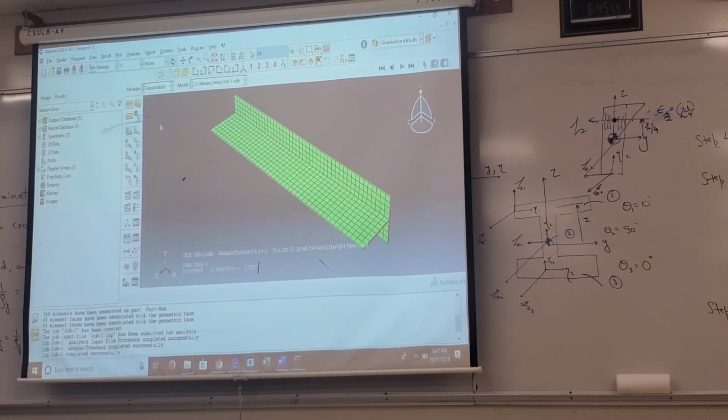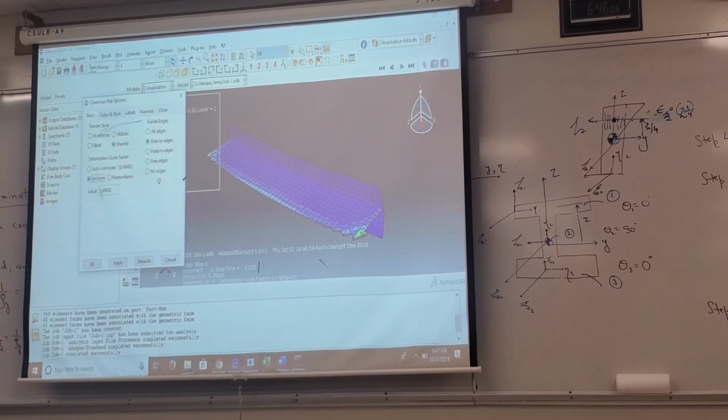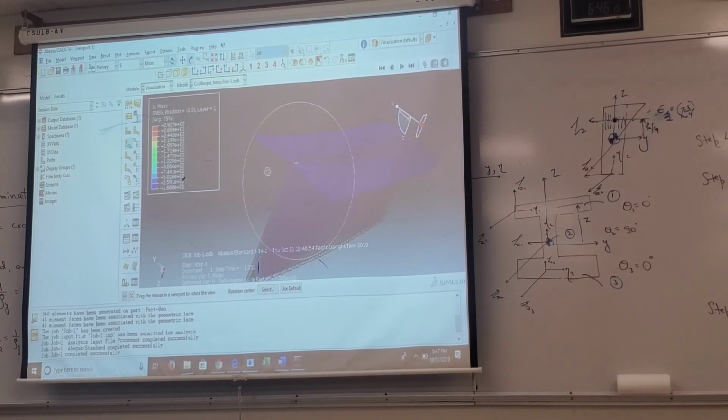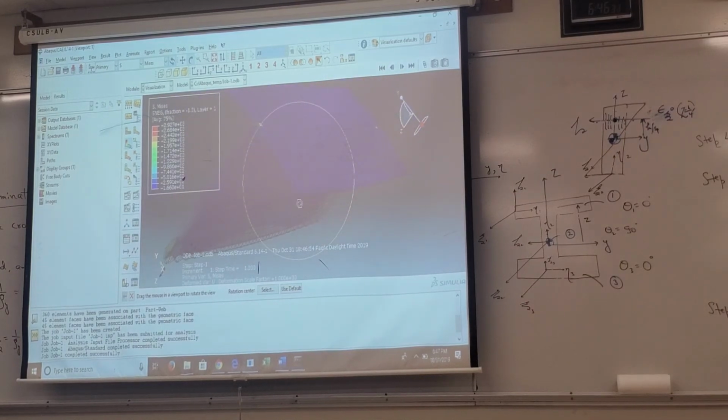So if I see the results, you see our deformed shape. First thing you have to do is go to options, common, and select that as one scale because it will not be an accelerated mode of deformation. So this is basically the deformed state for individual plies. Now you will see that the plies are stacked in the manner we need it. So for the web, you have plies vertically, and for the flange, it is horizontal. Okay? Does it make sense to you guys?